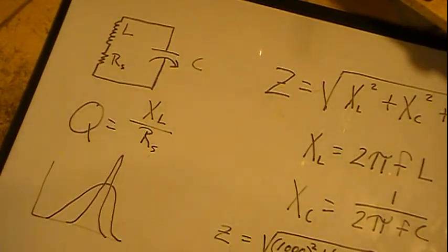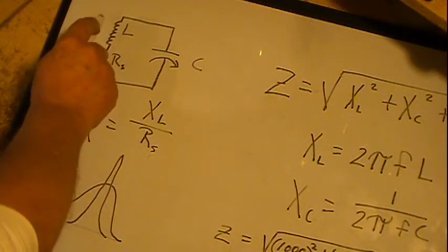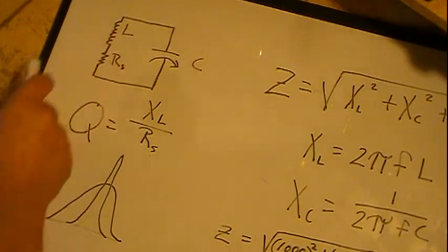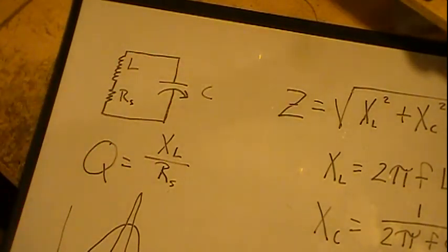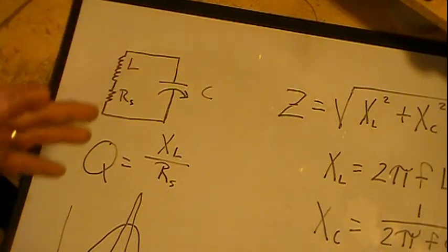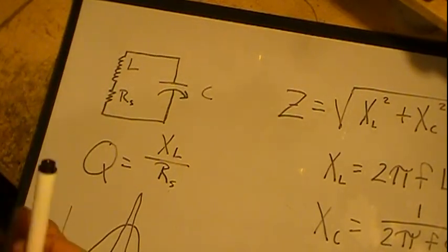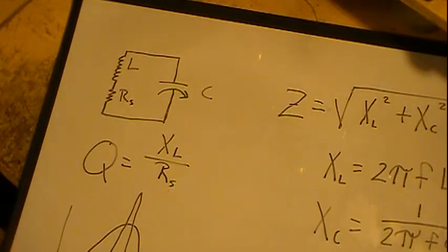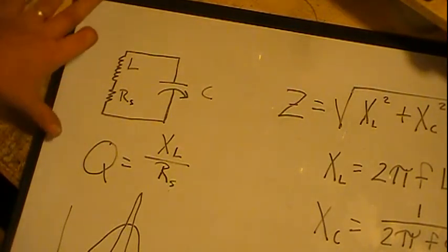Now that's about all I'm going to say on this. The big point was, don't get really concerned about the resistor. Worry about your inductance. Make sure it's correct, because that's what's going to be setting your resonant frequency. If you get it off too much, you won't have any adjustment in any of your padders or trimmers to get the radio lined up. So then it won't be working properly for you.